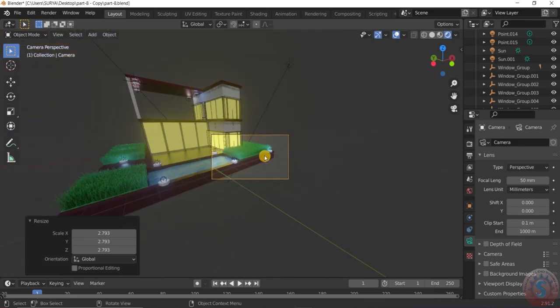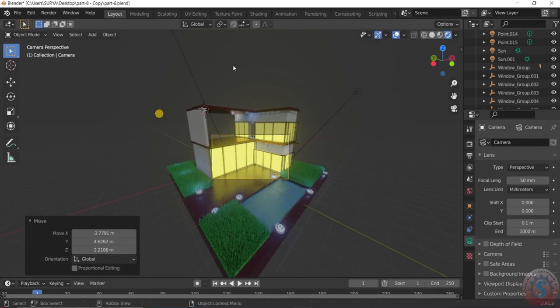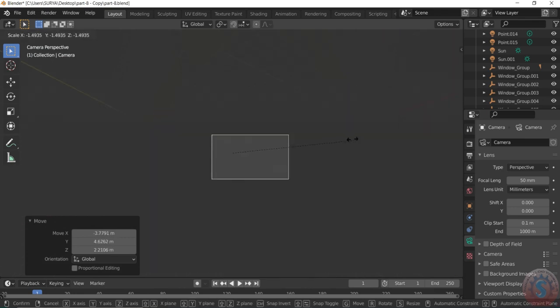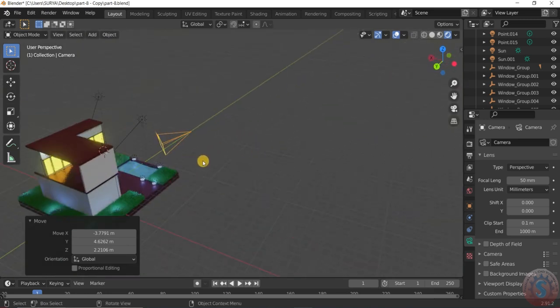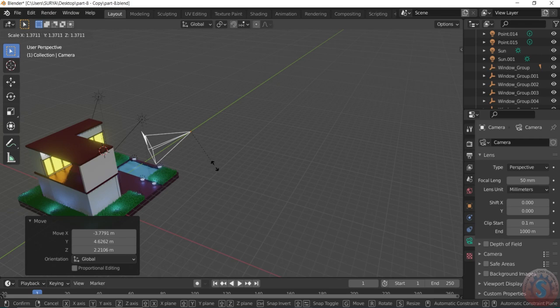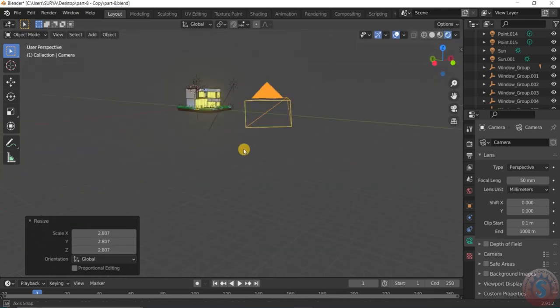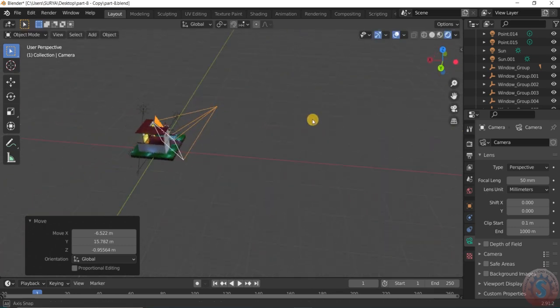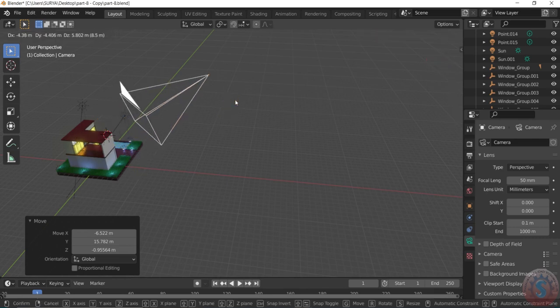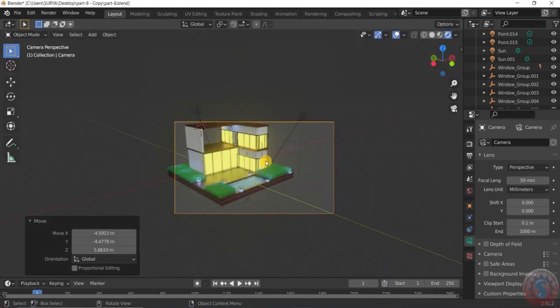You can observe I am selecting the G option here. Again scale the camera, pressing 0, and scale the camera somewhat larger and move this camera on the Y axis. Again S and give the position to the camera like this, leave the G option and press 0.